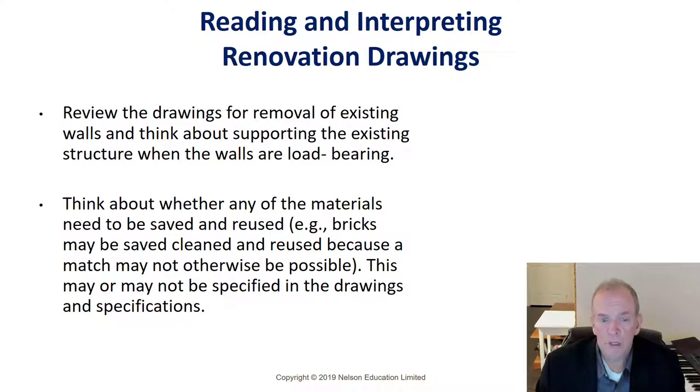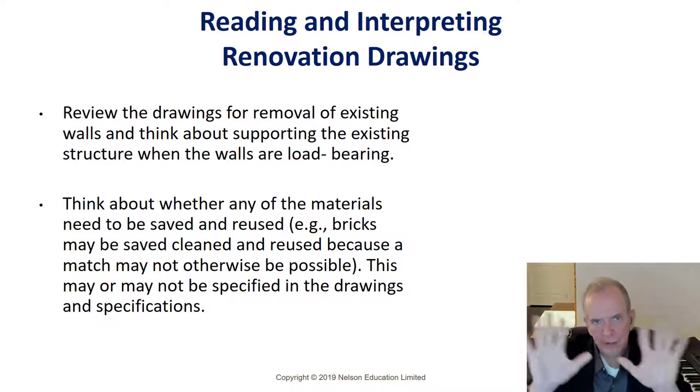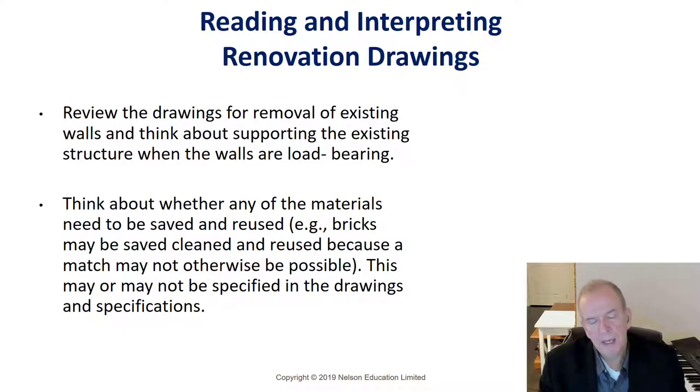If you have the opportunity when you're renovating, you might be able to save some of the brick that you take out and clean them. It's not that bad to clean them. You chip them with a brick hammer and basically the mortar comes off and you can pretty much reuse them. So say you had a window that was being bricked in and you were opening up the back of the house, you could save the brick from that to fill in the window, and you could make it look like it's perfectly fine, like there's nothing wrong with it. So the interpretation would be looking at it and it'll look like it was almost always there. Some of these things seem like small things, but they make a huge difference in the actual construction process.